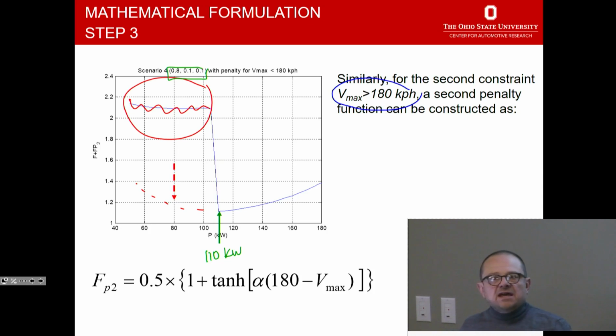Notice that in this case, I have imposed the constraints after having created the cost function. You might then say, wait, is it possible? Could I, instead of having a cost function that has weighted fuel economy, acceleration, and top speed, could I just simply minimize fuel economies but impose the constraints on top speed and acceleration?